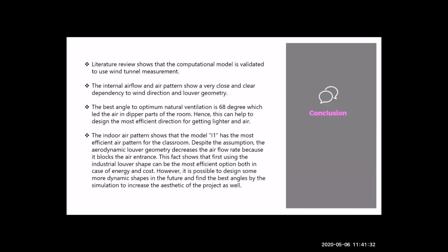And as a conclusion, this paper describes the development of a CFD simulation for use in analyzing the impacts of louver geometry and wind direction on cross-ventilation airflow in a generic isolated classroom. The simulation analyzed the 5 different wind directions and 5 different louver geometries to show the indoor air pattern. Based on the simulation of the generic isolated classroom, this study has 4 main conclusions.